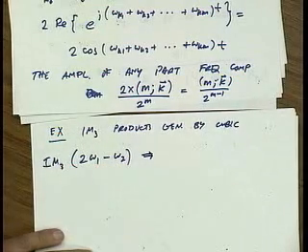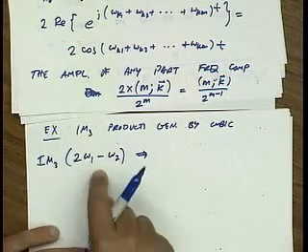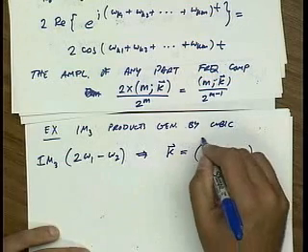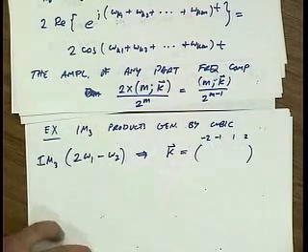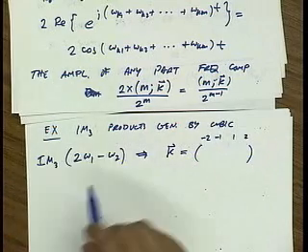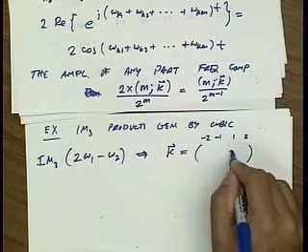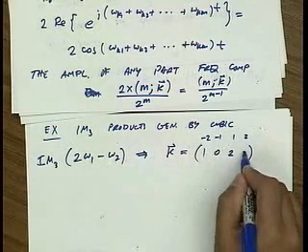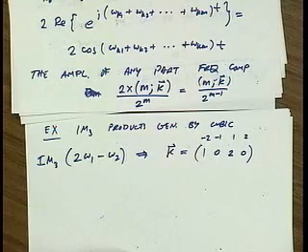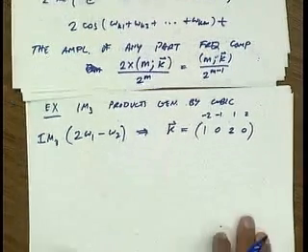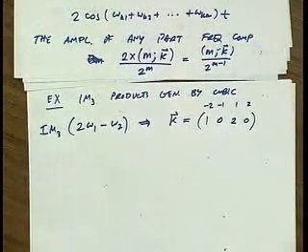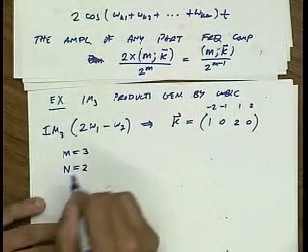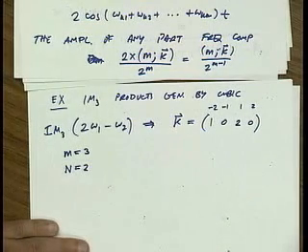Well, first thing we do is we write down the k vector for this particular IM3 product, and I write down my columns here which tell me which frequencies I'm interested in, and we did this already. This has 2 frequency omega 1 and 1 frequency minus omega 2. So this is my k vector. Okay? Everybody see where that came from? Yeah, good. Now m is equal to 3 and n is equal to 2 for a two-tone test, right? I should have said that first.